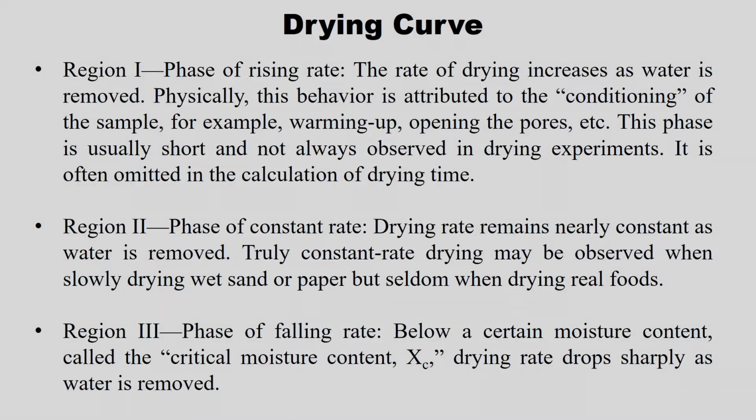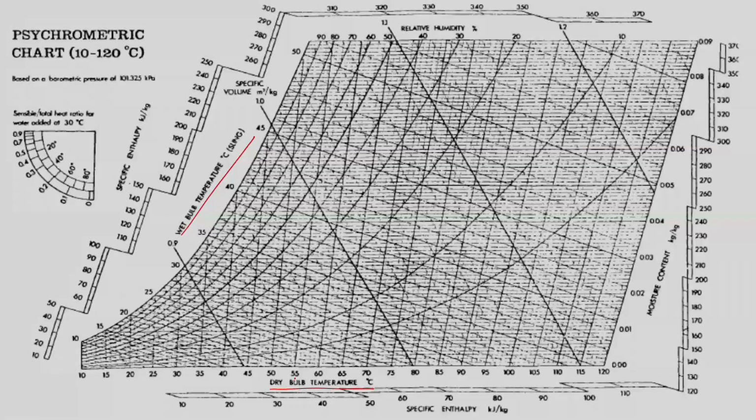For example, if I fix my dry bulb temperature as 55 and my wet bulb temperature as 35. So, the 35 line is here, right, and my dry bulb temperature of 55 degree line is here. If you keep this, from this I can calculate relative humidity. How? This is the 30% relative humidity line and this is the 20% relative humidity line.